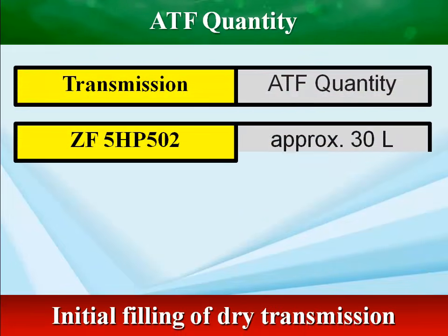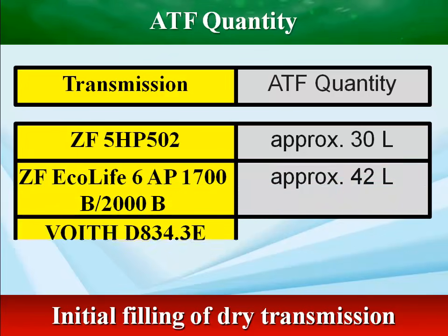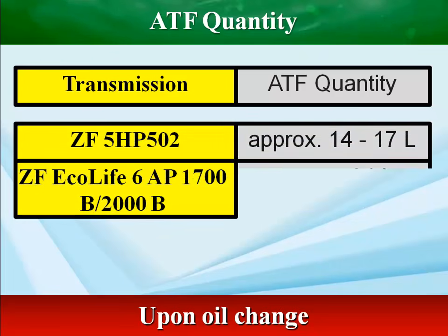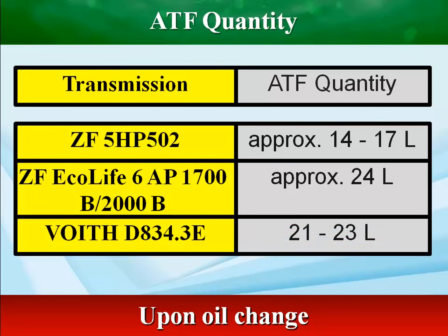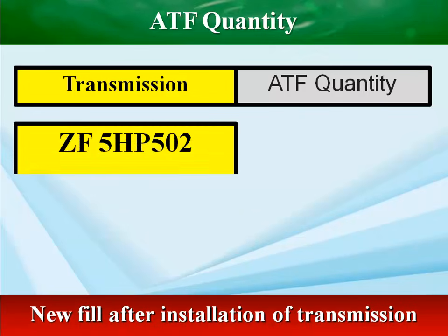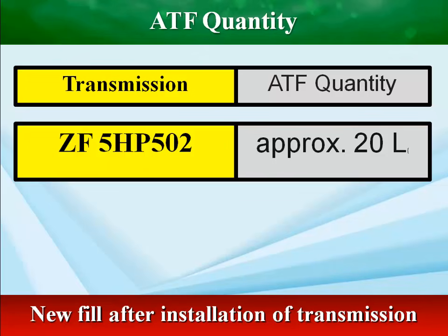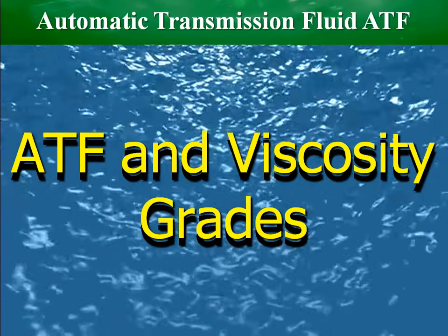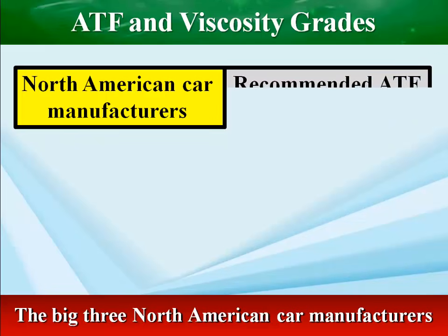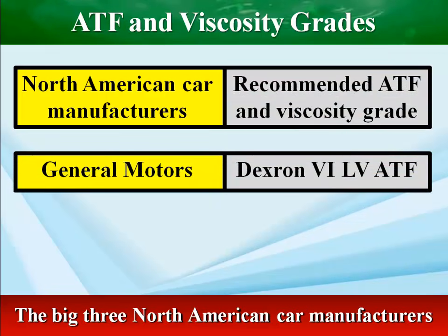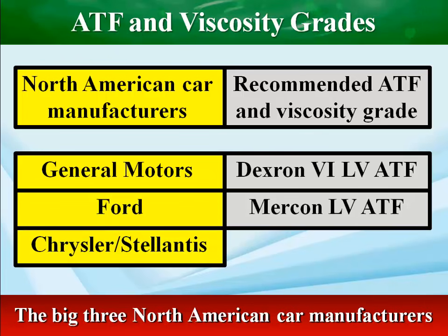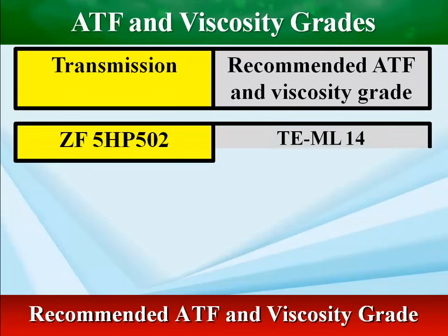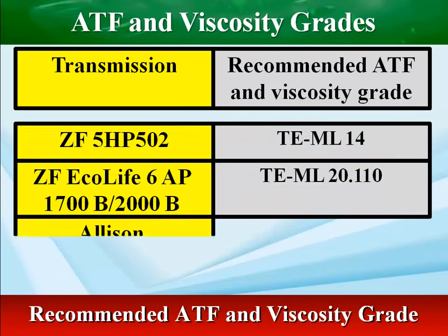These values are reference values. The definitive quantity is the one determined by the fluid level check at operating temperature. Only use approved viscosity grades, following the manufacturer's recommendations. When choosing the optimum viscosity grade of fluid to use, geographical location must be taken into consideration.